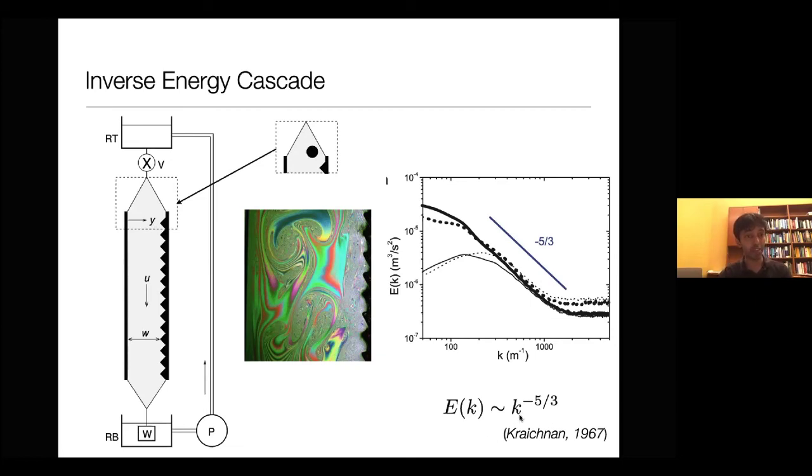So we can confirm that just by changing the entrance of the channel, we can make the flow switch to one of two theoretically possible spectral exponents, 3 or 5/3. The rest of the techniques are exactly the same. The channel is exactly the same. All we are doing is playing with the entrance so that we can pick one or the other. It's like you have two basins of attraction and you're picking one or the other.